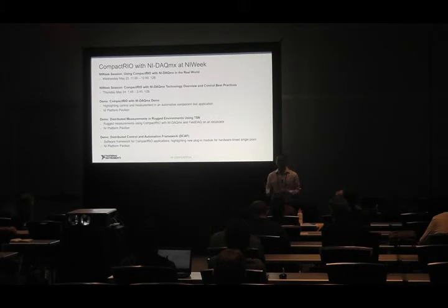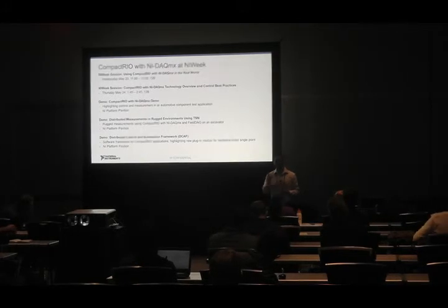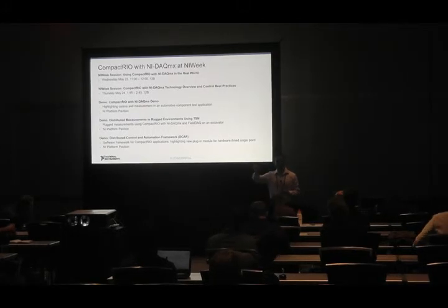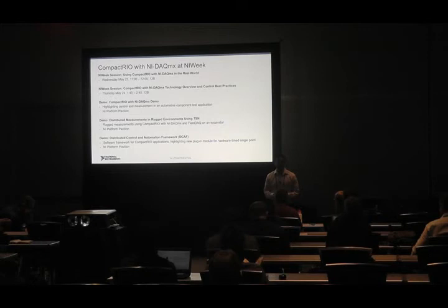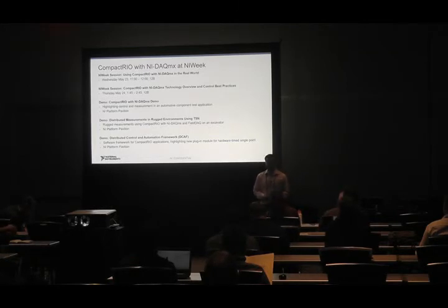So let's say, for example, you already have an FPGA application, you want to add some waveform measurements to it. You can do that in DAQmx. It'll be a completely separate route, so it will consume 0 FPGA space. And it's a separate hardware-based route that gets you data back very quickly, like you would expect, and is now also deterministic if you wanted to do some control there. So from a FPGA side, using DAQmx doesn't consume resources, and vice versa. If I add an FPGA when I'm using DAQmx today, those are 2 completely separate things, and both can be used.